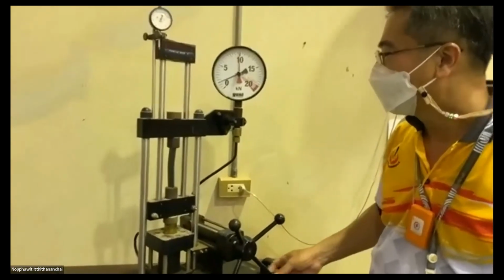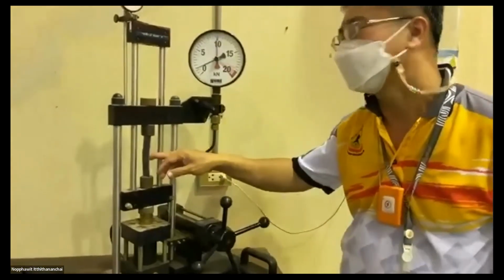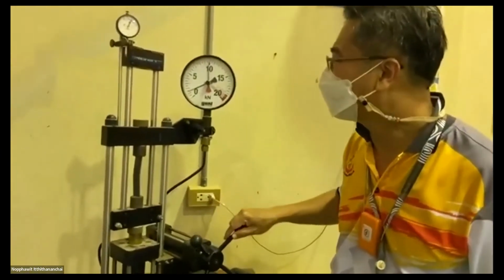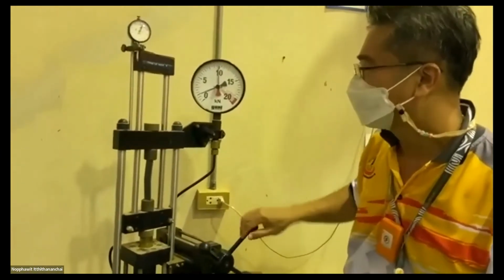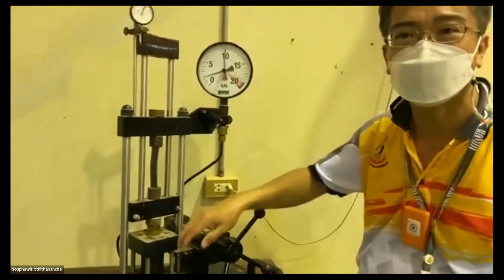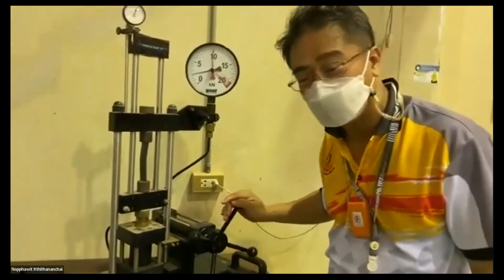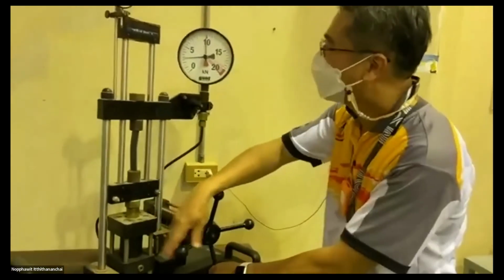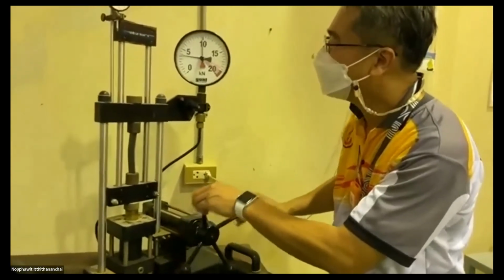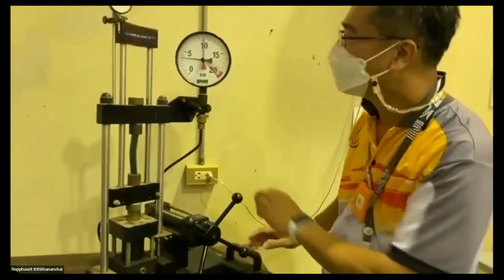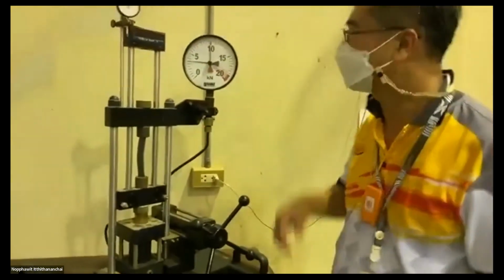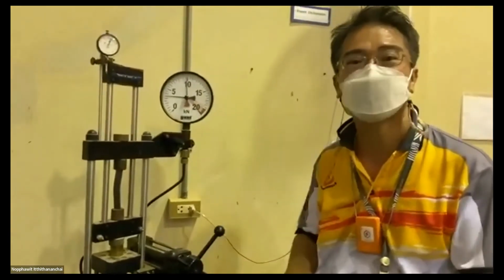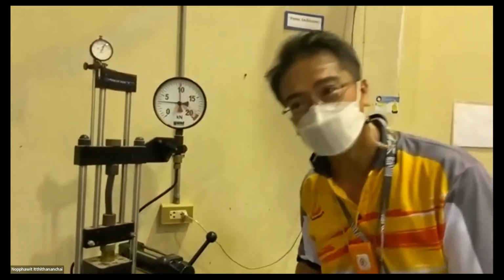And this is not really the total failure. If you increase the load again, you may see the column is able to take some load. When you increase it continuously, it will not reach the previous point, but it does not totally collapse. It can still take some load.